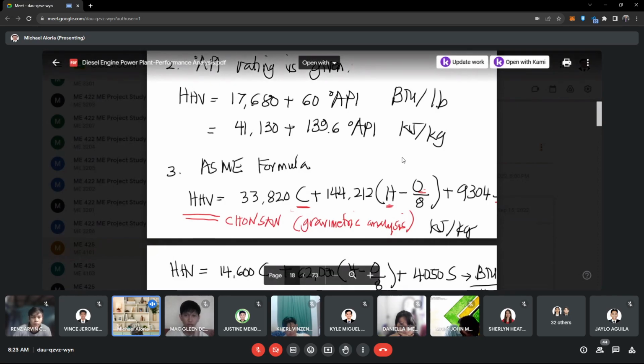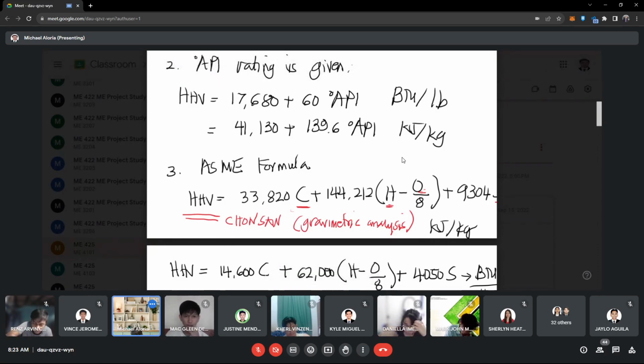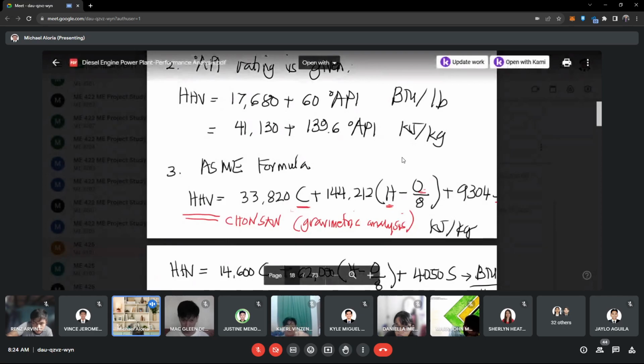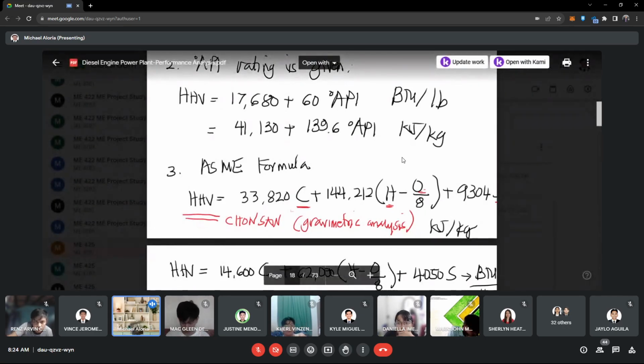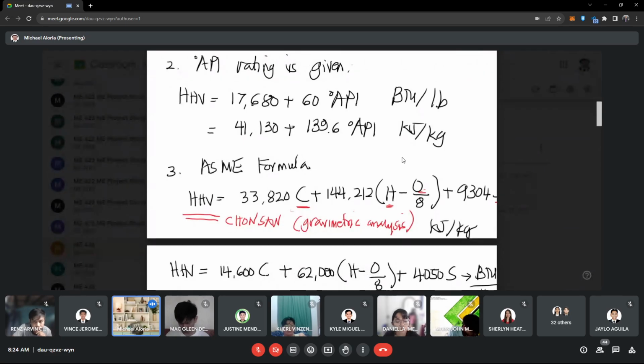I repeat, 33,820 times your carbon from the ultimate analysis, plus 144,212 times your hydrogen minus oxygen over 8. Hydrogen and oxygen are also taken from your ultimate analysis, plus 9304 times your S. And S should be taken also from your ultimate analysis.